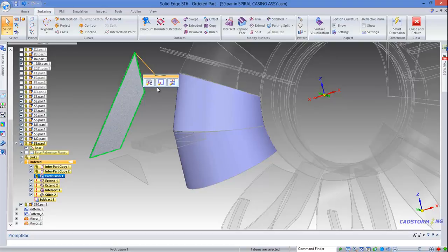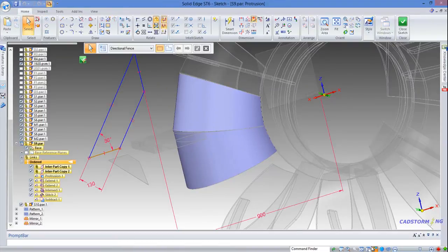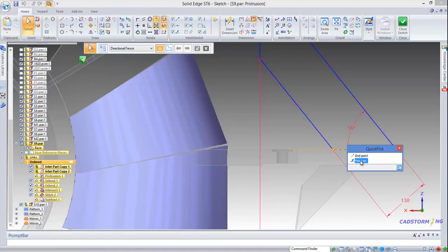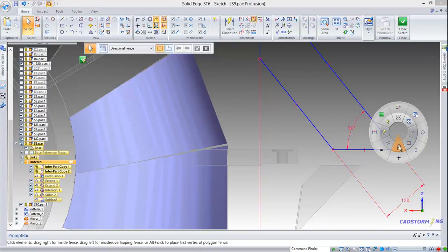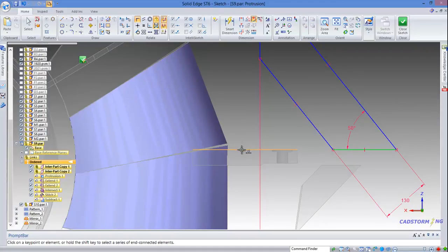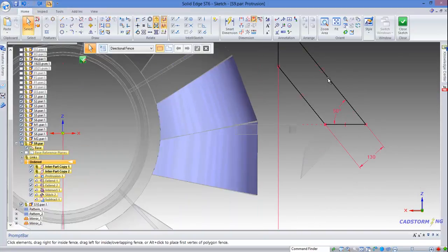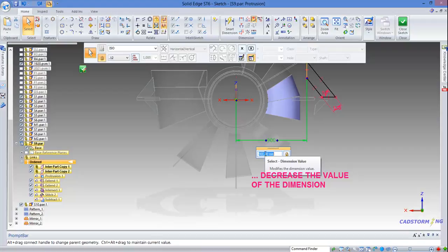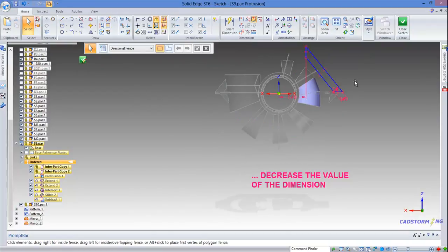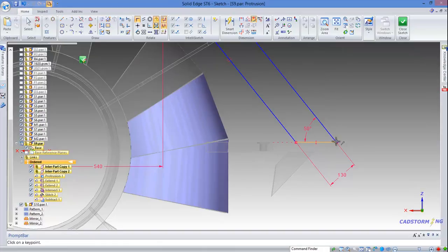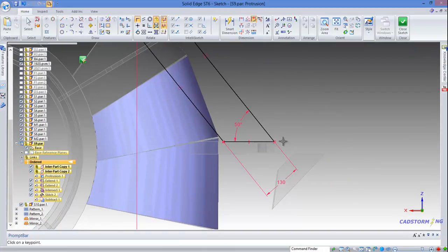Now we reposition the protrusion, so normal 2, and as we did before we are going to remove the point on constraint and on this endpoint 2, and we are going to reapply them, this point to this edge and this point to this endpoint, and it doesn't work like expected, so we will undo and maybe first move this like that, so to 540, and now we will connect this endpoint to this one.